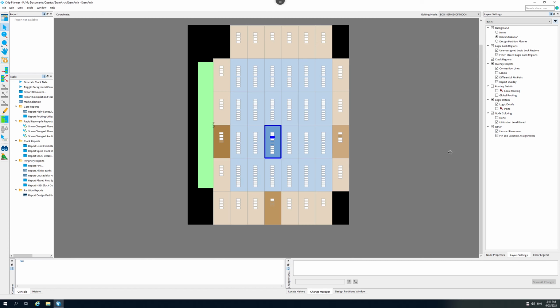If I turn the unused resources back on for a moment, then we have around the outside our input-output blocks, and inside in blue, these are our logic array blocks. So I like to think of them as apartment buildings. We have 10 tenants to each apartment building. Belonging to the same apartment building means that you share the same plumbing, you share the same electricity, the water pipes, etc. And information can be transferred quickly between these tenants because they all live in the same set of apartments.